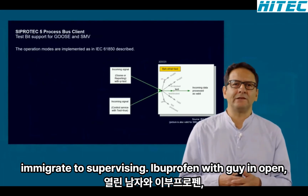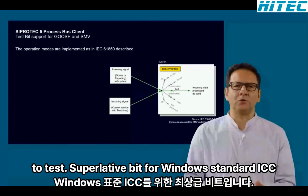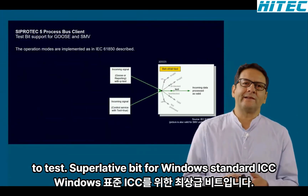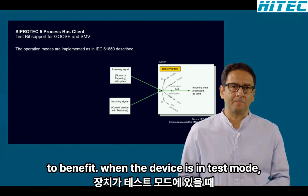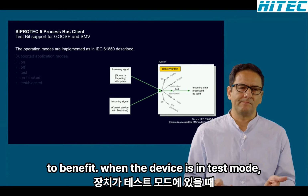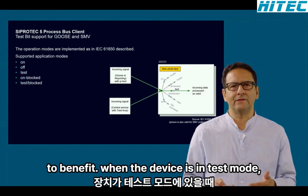CProtect Process Bus Client also offers the option to test. It supports the test bit following the standard IEC 61850. The supported application modes are on, off, test, unblocked, or test blocked.